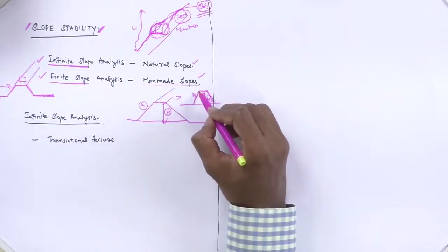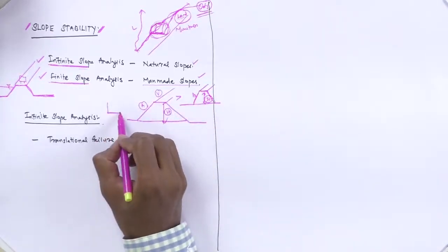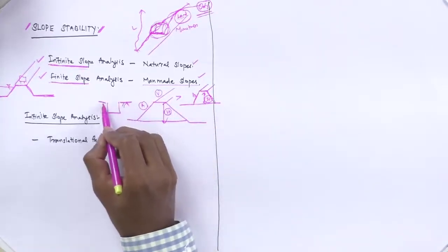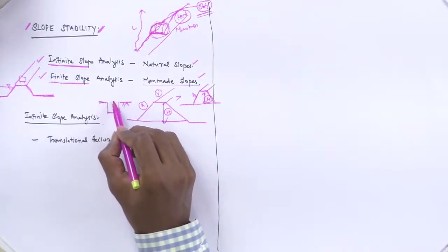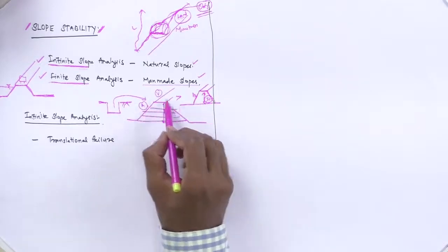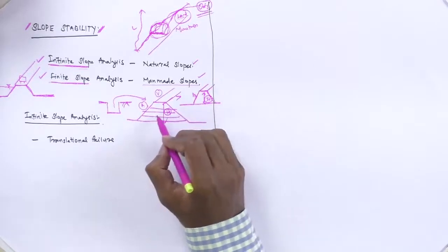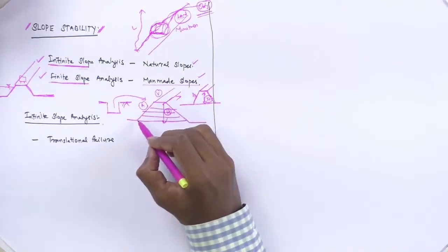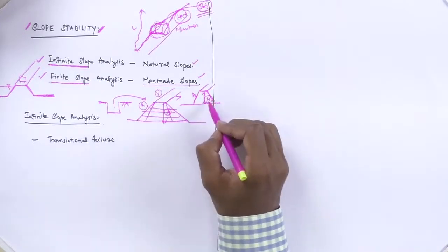This runs for several distances, so the volume needs to be borrowed from an earth pit. A borrow pit is going to be dug, the collected soil has to be transported, compacted, and filled to form this finite slope. When you make the slope steeper, the area is reduced as shown here.